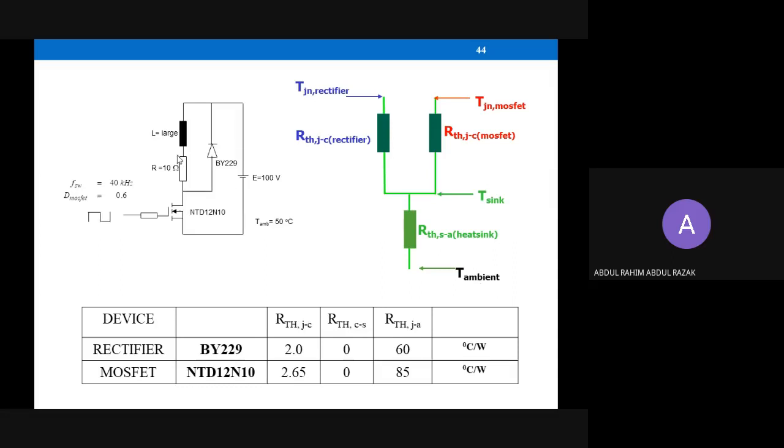in this scenario? As I mentioned before, we need to find out what current flows through this MOSFET. Then you are able to know the PD. From the circuit we find out the current, then PD, and also the TJ. With that, we are able to conclude whether the heatsink is sufficient or not for the system.